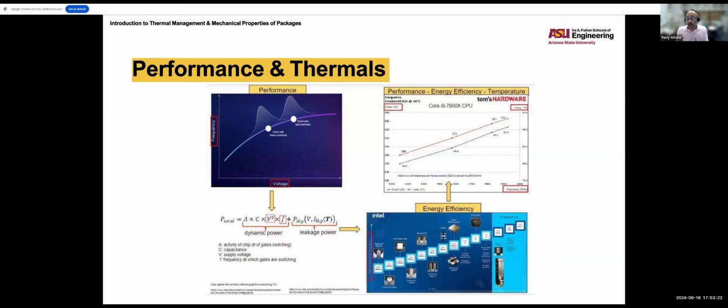Now we're talking about the CPU being up to 120, 140 degrees C. Very dangerous regime because the CPU is meant to operate in a very specific temperature range. And if we start driving this temperature as a function of frequency beyond the operating range, we have the possibility of destroying the part.